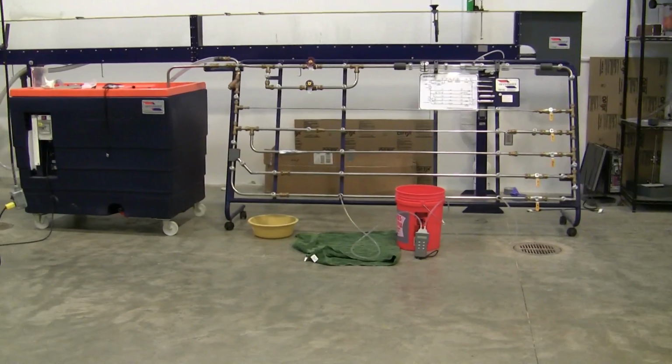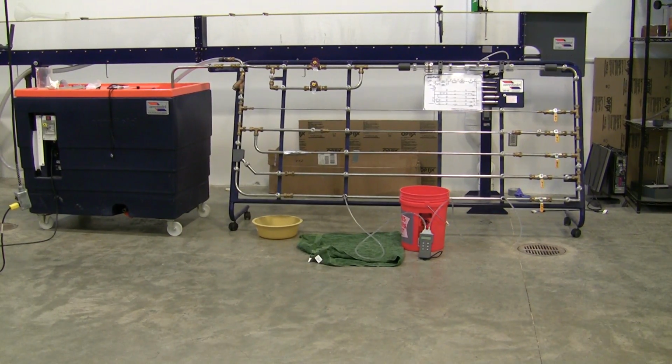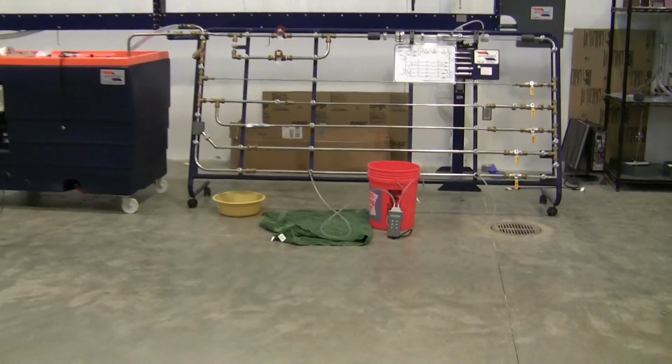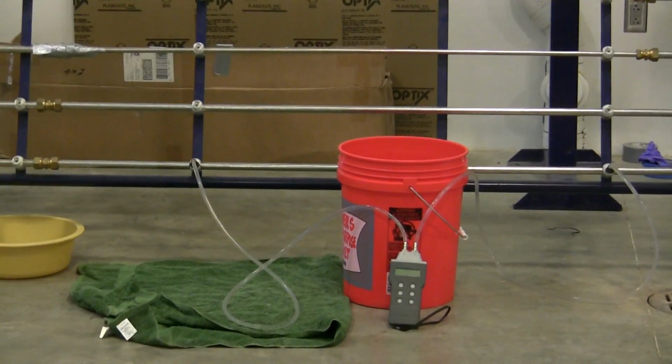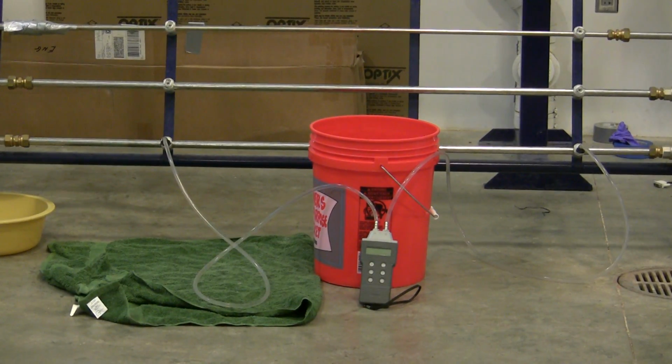A couple of auxiliary items are shown there. You can see that there is the red bucket. The red bucket is used because it's important to purge air out of the lines that are connecting from the tap to the pressure measurement device. If little air bubbles are in that, then there can be additional fluctuation and it introduces an element of error that we want to eliminate. And so when a tap is plugged in, I'll periodically check for air in the lines, and if air is observed, then it'll be purged out of the lines into the bucket.